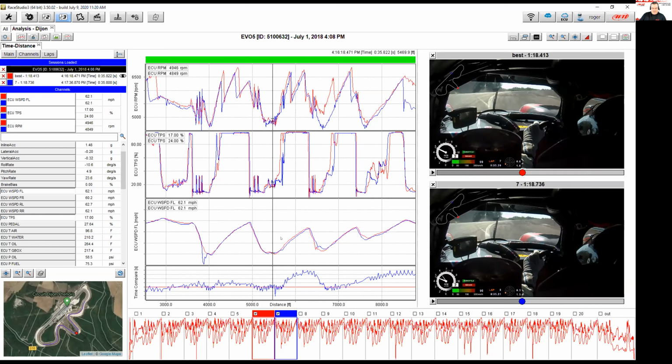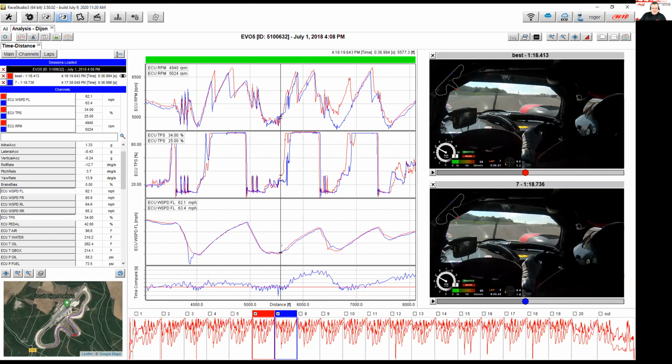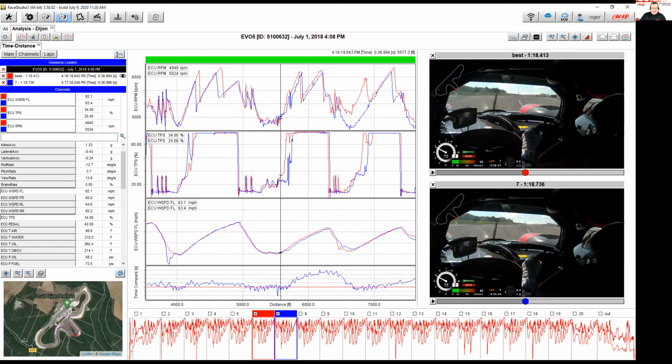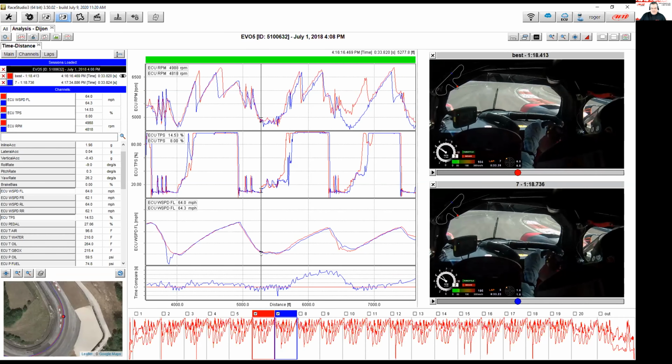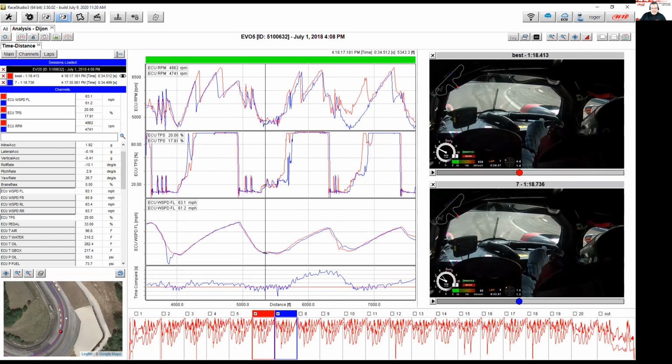In this case, I'm going to zoom in a little bit on this corner, just to make it easier to see. We're going to zoom in on the location down here on the GPS map below, with the Google Earth background imagery on it. Now I'm clicking in the strip charts in the measures graph and dragging this along. So we're looking at the entry into this corner in the lower left. If I zoom way in, we can really pick up where the driver went a little bit right on entry, and a little bit tighter on the apex as he's coming down in there.